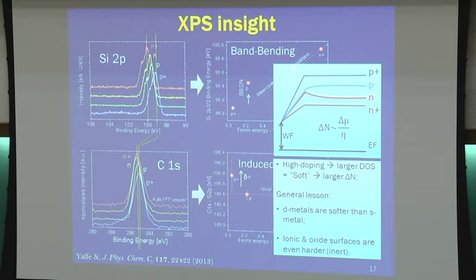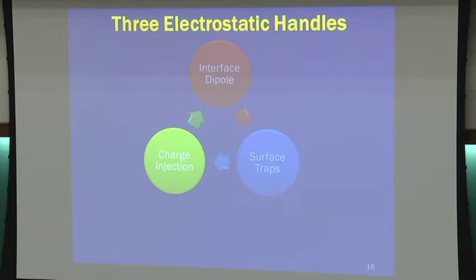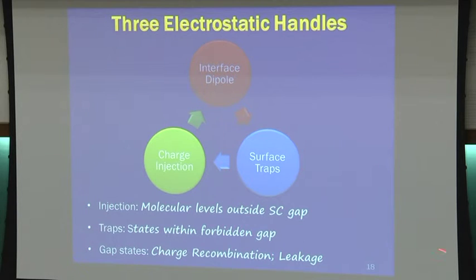It will be the smallest. It would be the largest on the highly doped P because of the charge rearrangement. And in the moderately doped, we'll have some band bending. That's what I show here. So there would be interplay between the band bending in the semiconductor and the potential drop on the molecules, and the anchor here is the work function of the molecules. So although these are kind of isolated molecules, no free electrons, they do have their own electrochemical potential, and it forced the energy alignment. So this brings me briefly to the last topic of surface traps.